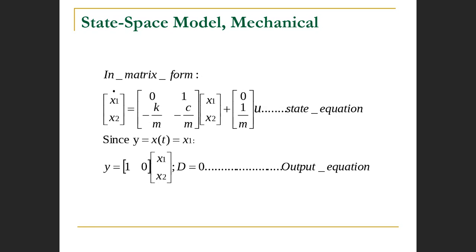All right, so we have so far looked at two systems, an electrical system and a mechanical system, and it's the same approach in terms of how we structure the state space equation. When it comes to a mechanical system, it's always easy to choose the state variables in this fashion. If the output is displacement, you could choose displacement and velocity or any other such independent variable. All right, go ahead, Richard.